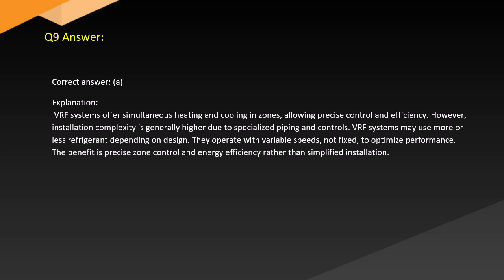VRF systems may use more or less refrigerant depending on design. They operate with variable speeds, not fixed, to optimize performance. The benefit is precise zone control and energy efficiency rather than simpler installation.